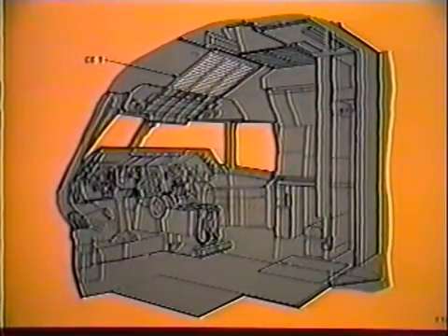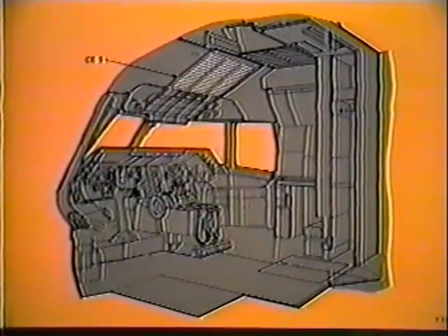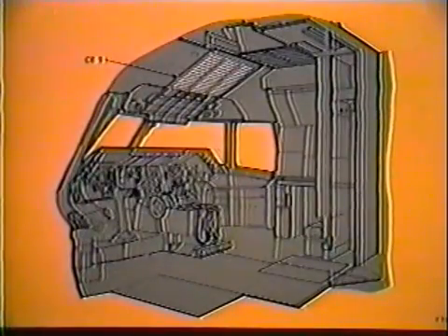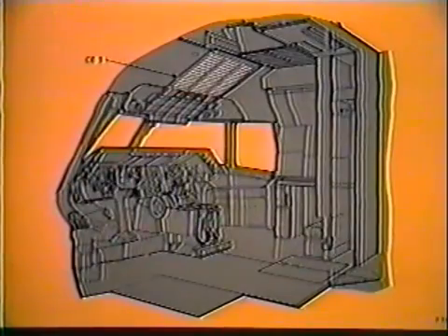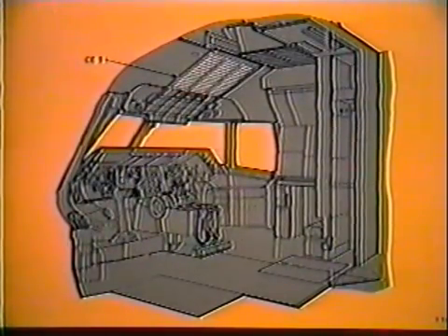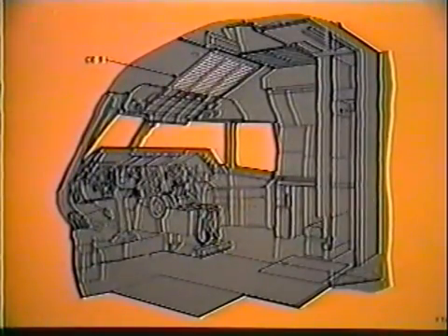Since circuit breaker panel 1 is within reach of both pilots, the left side contains the captain's flight instrument and avionics circuit breakers, and the right side contains the first officer's flight instrument and avionics circuit breakers. The center column contains circuit breakers pertinent to all 3 crew members.